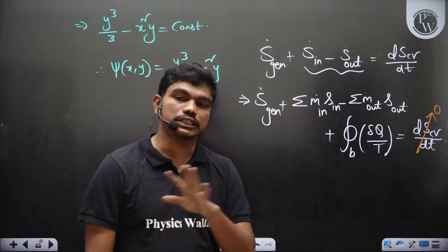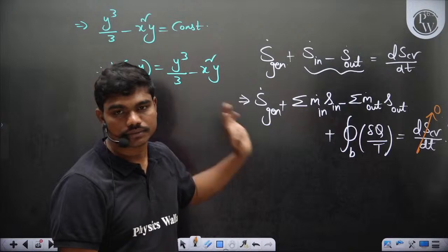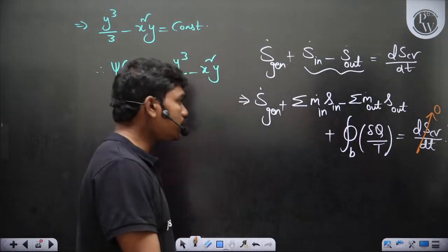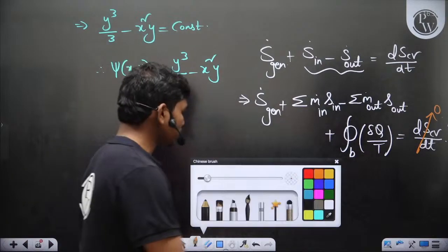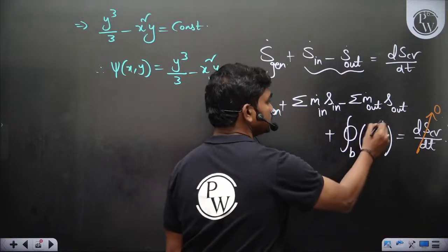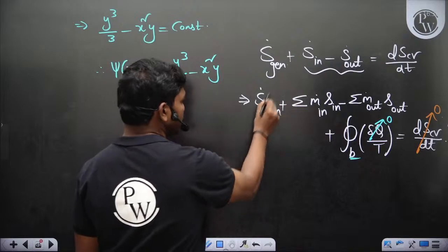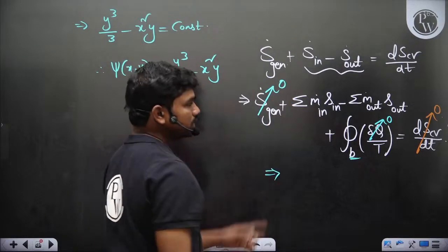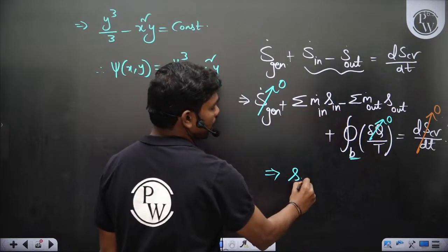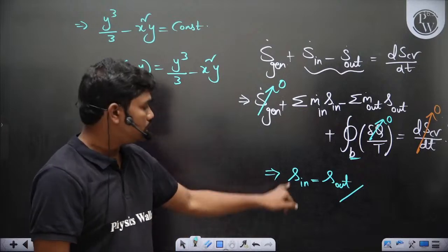Okay, if the process is happening irreversibly and at steady state, then this term is also 0, otherwise you cannot decide. For example, you take an insulated turbine operating at steady state, adiabatic, closely insulated, then this del q is 0 across any point in the boundary if you insulate the turbine, and if there is a reversible expansion, so this is 0, and steady state, so m dot in is the same as m dot out. That's how you have s in equal to s out for turbines.